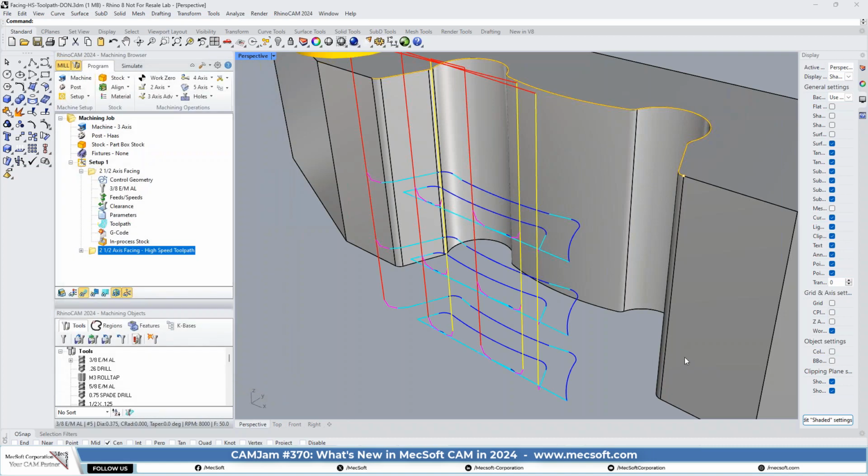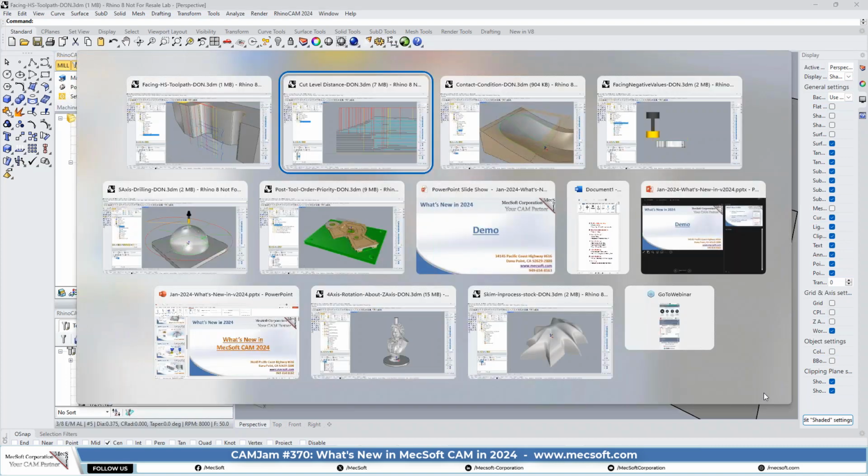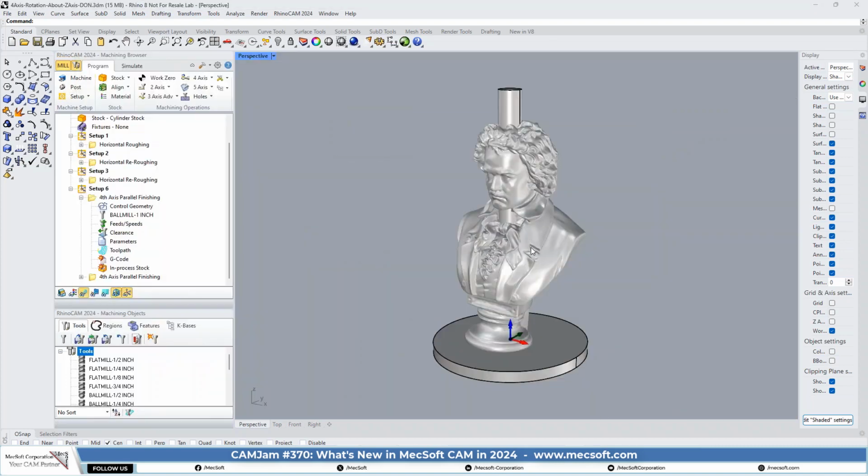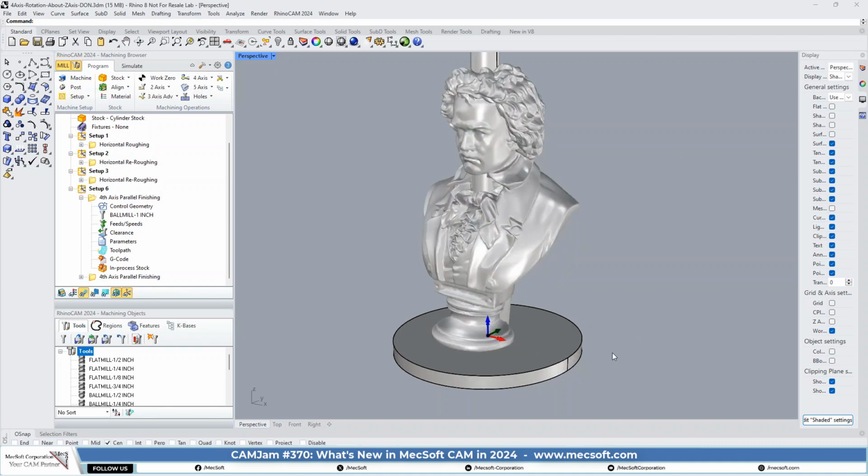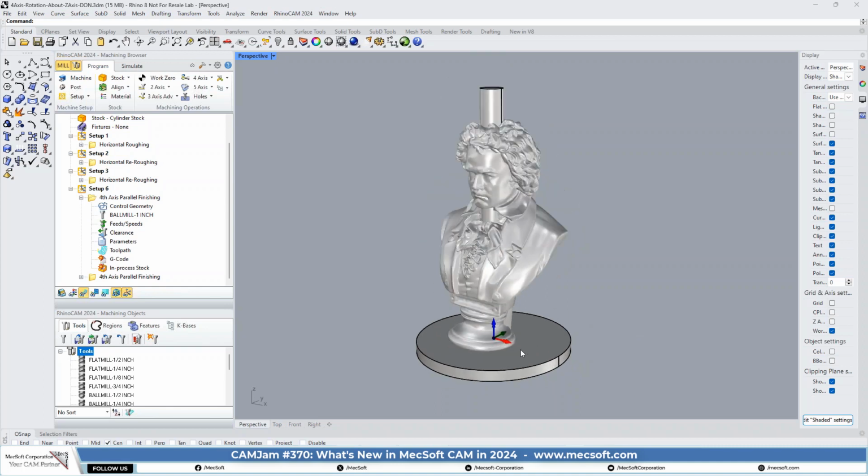Okay, so let's go on to 4-axis. If I missed anything, Joe, just let me know. Basically in 23, you couldn't do the 4-axis with the part aligned the way it is right now. You would have to roll it over to extend either in the X-axis or the Y-axis and perform the extra. Y would be the rotary axis, and then you would only be able to machine it in that axis.